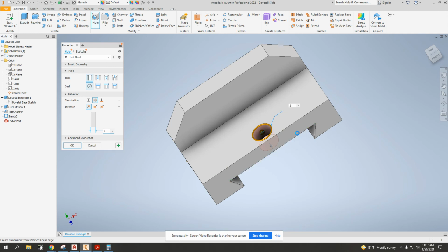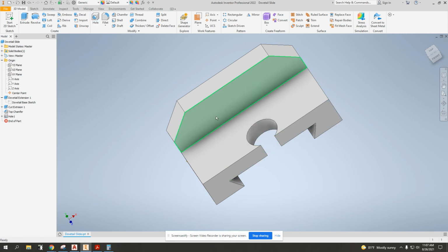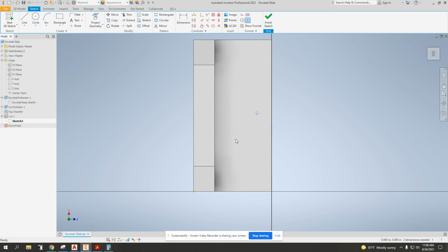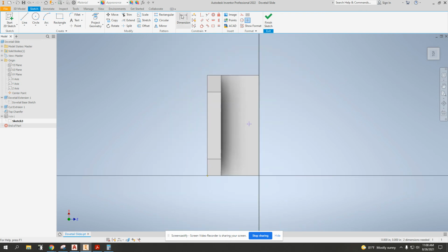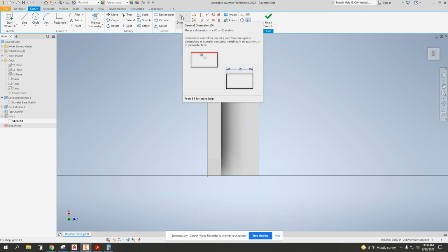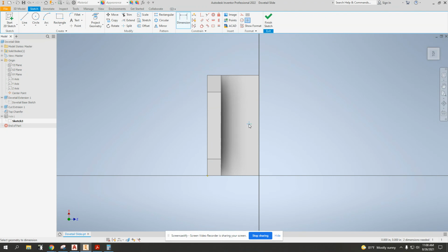Let's do this. Let's make that hole 1 inch. So it's the right size, except I just ended things. And we'll notice here in the model browser on the left, under hole 1, I expand it and there's a sketch. Now I'm going to edit that sketch. So now I'm in the sketch geometry for this object. And what if I dimension the center of that hole? Let's try that. Let's go from center to here, and that was supposed to be, let's go check,